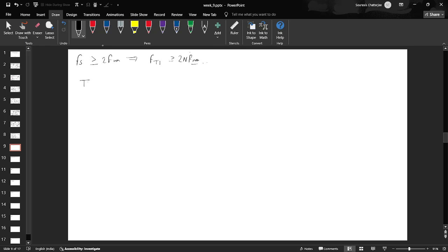So the T1 system uses a mu law quantizer. What is that? You can refer to that lecture actually. What is important here to know is that the mu law quantizer uses 256 quantization levels, and that is our useful information.